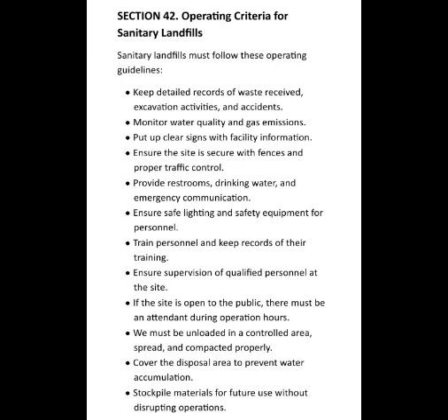Section 42, operating criteria for sanitary landfills. Sanitary landfills must follow these operating guidelines: keep detailed records of waste received, excavation activities, and accidents. Monitor water quality and gas emissions. Put up clear signs with facility information. Ensure the site is secure with fences and proper traffic control. Provide restrooms, drinking water, and emergency communication.